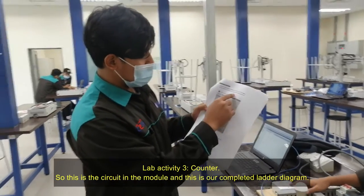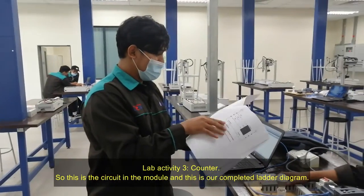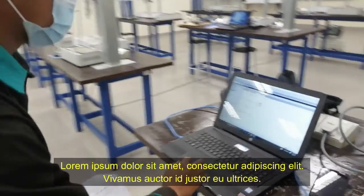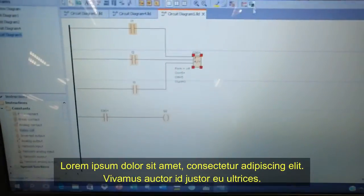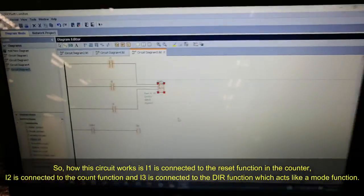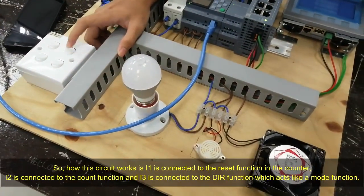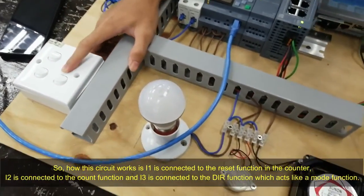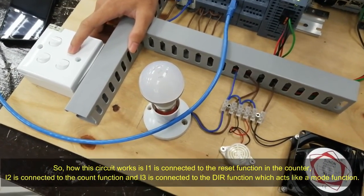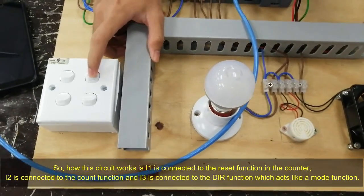Lab activity 3, counter. This is the circuit in the module and this is our complete ladder diagram. So how this circuit works is I1 is connected to the reset function in the counter, I2 is connected to the count function, and I3 is connected to the add function, which acts like a mode function.